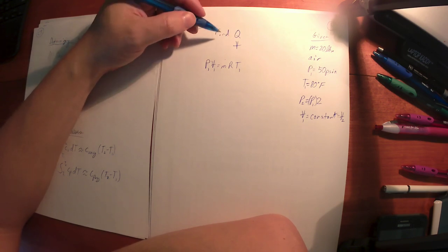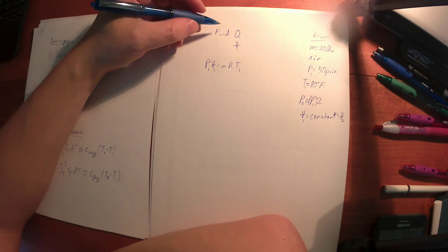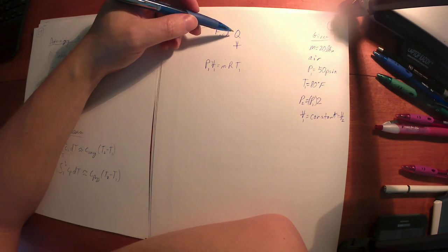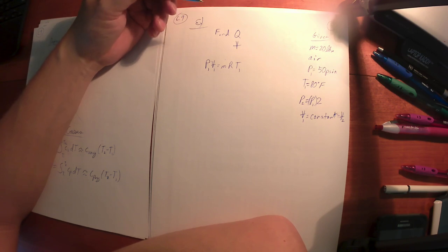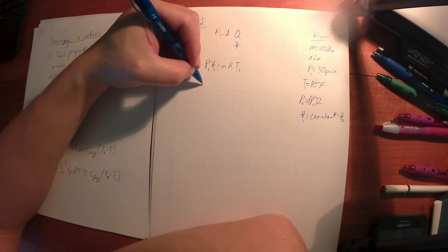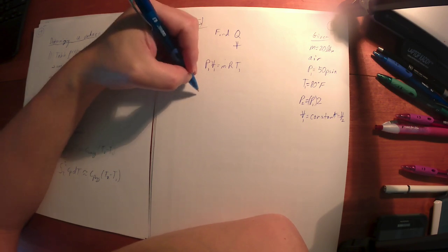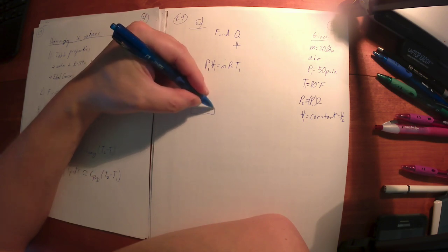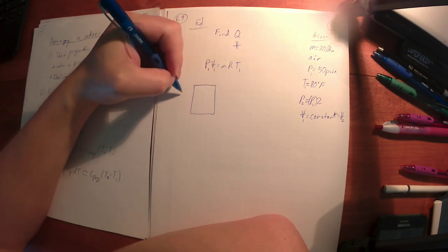What is a good tool I might have to find the heat transfer? It might be a little early in the class, but in the very near future, when I ask you how we find an unknown heat transfer or any kind of unknown energy, it needs to be a gag reflex: first law. First law is always the first thing we'll try to use to find an unknown energy. So how do we write a first law equation? Well, the first thing you do is you draw your system.